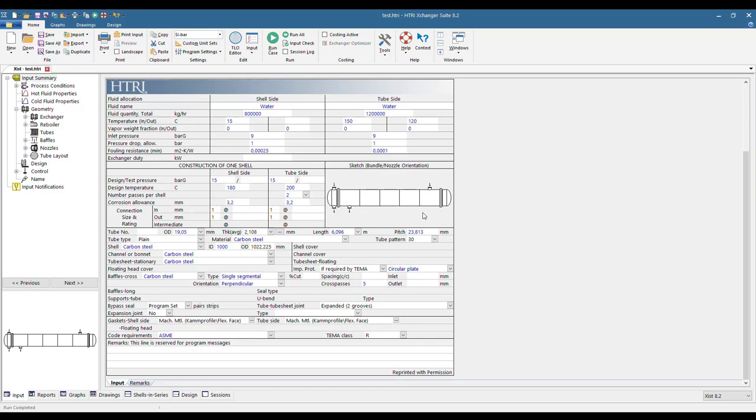So why has this decision been taken instead of specifying a baffle pitch? Because in any case the program makes some kind of calculation of this spacing, since these spacings are in a certain way obliged by the need of having nozzles here and here.